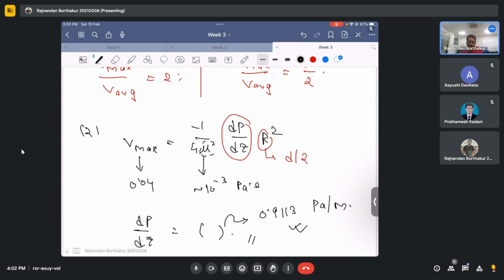In fluids, viscosity is related to the cohesive forces which act between the surface in contact with the fluid and the fluid itself. However, in gases, the cohesive forces don't come into the picture, and something else occurs in gases. These are completely different physics, and that's why viscosities of liquids and gases show different trends when we increase or decrease temperature. So this is the idea behind this.